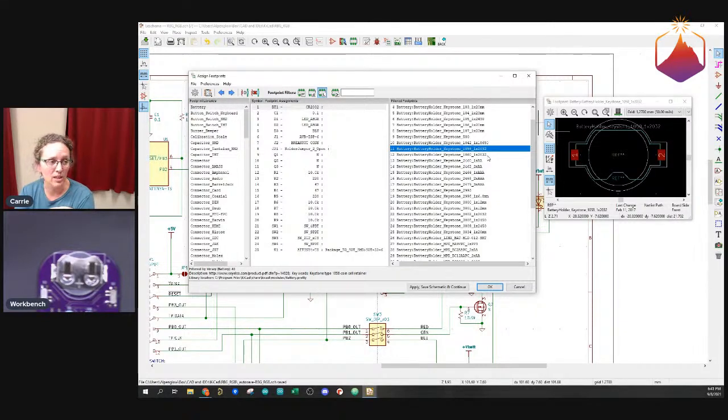Because he's probably done some boards with that style of connector. And so he might be like, oh yeah, we have to run that at a higher temperature or whatever, or for longer. Like he might've figured out there's a way of processing this type of connector that makes that solder joint fine and not a problem. And it's really helpful when you can actually talk to a board house and ask them those questions. That's one problem with the consolidator services, that it's hard to get answers like that. It's hard to talk to a human and get that kind of specificity of information.